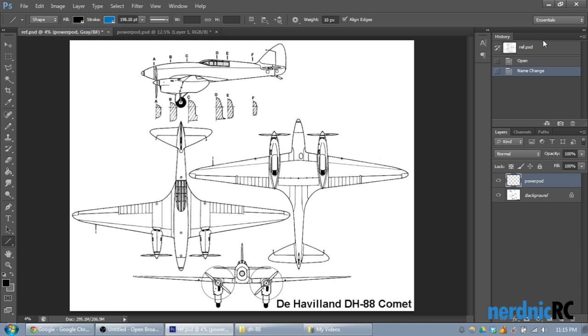We've already got the proper size of our airplane. We're looking at about a 40-inch wingspan with this scale right now, which is what I'm aiming for in terms of size. My goal with this plane is to design it to allow for 2 different size motors. One setup being 3-cell should push the plane in the 60s or so, and then the other setup should push it with 4S just over 100.